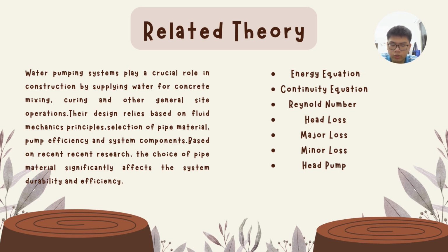Firstly is the energy equation. We can also know it as the extension of the Bernoulli equation to analyze steady incompressible flow, correlating pressure, kinetic energy, and potential energy, which is also known as the elevation. The complete formulation includes the energy additions from the pumping system and energy dissipation from both viscous friction and local loss throughout the pipes.